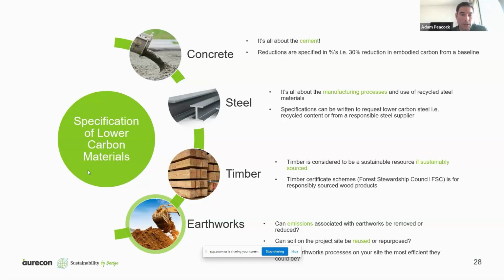And then the earthworks, it's all about trying to optimize the processes on site. So trying to optimize the cut and fill, trying to balance it out, trying to reduce the amount of double handling or having to cut off the site and then to transport it back to another site or back to the same site.